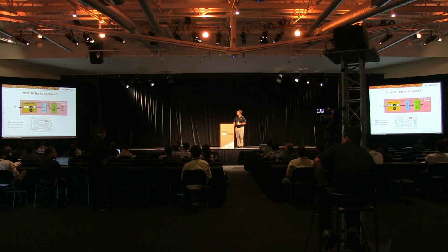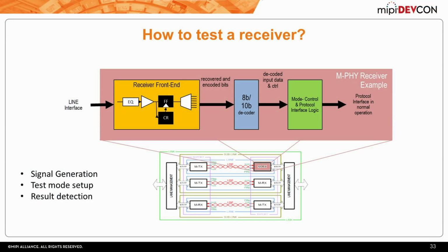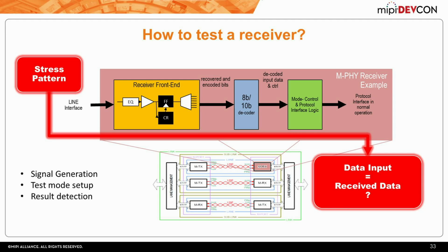All right, last subject here is talking about some of the challenges for receiver testing in the MIPI environment. We want to introduce a stressed eye, send in a known pattern and count errors. MIPI doesn't really specify very well that you have to have testability in your device. So a lot of devices don't have error counters, they don't have a loopback path, and that raises a lot of challenges for receiver test, is the bottom line.